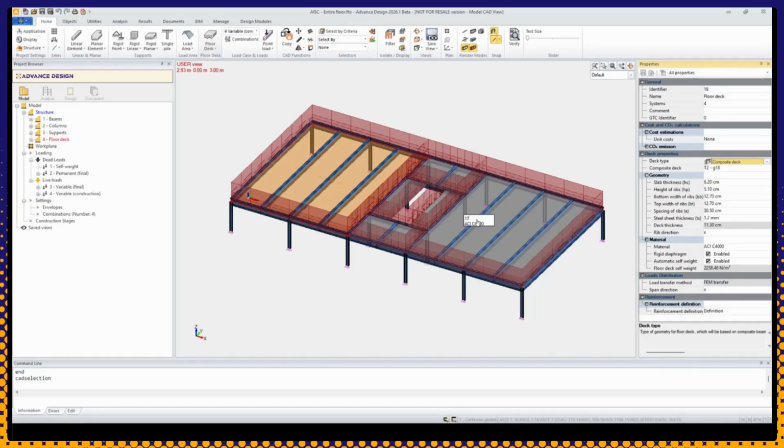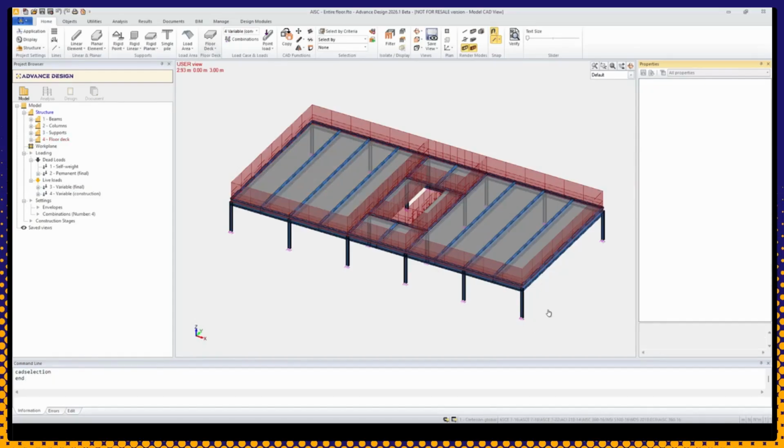And as you see here, I have a sign, these arrows that you see, which is showing that my deck is aligned correctly and it's distributing the forces on the composite beams. So after creating your elements and slabs, the next option would be you can define or check the parameters regarding the design and verification. You can always find them here.